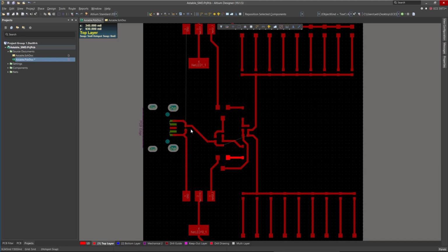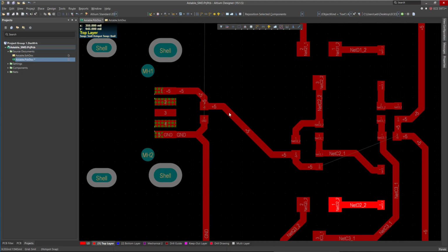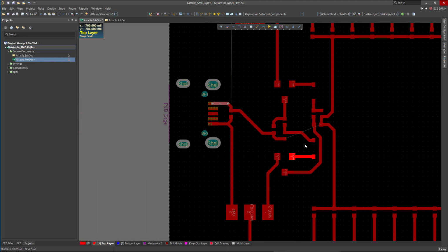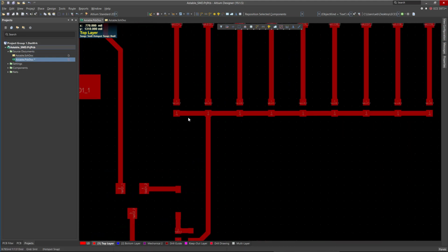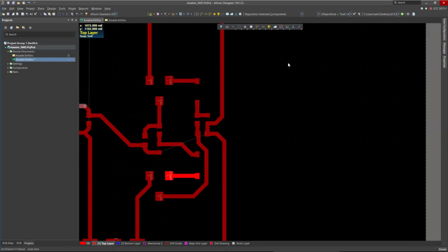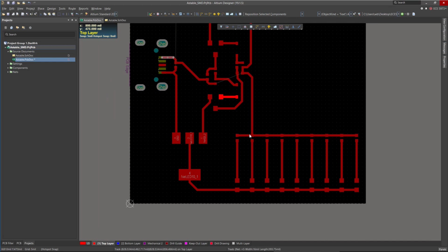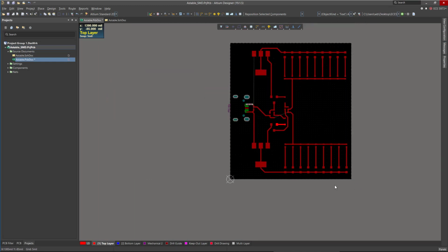This is a very important point to watch out for. This is your source supply. Basically your supply will come from the USB connector, micro USB connector, through this trace here, and from here your supply will distribute to the first set of the LED on the anode pin, and the second set of the LED on the anode pin as well.